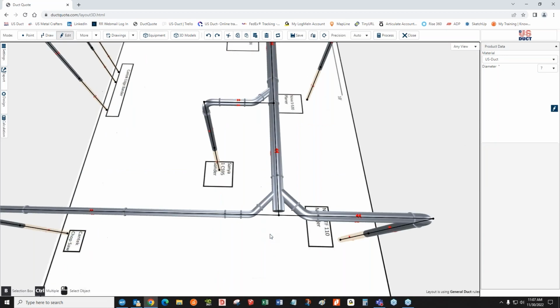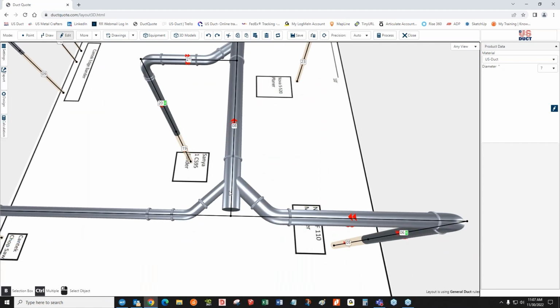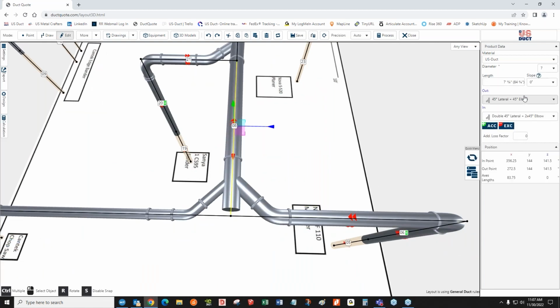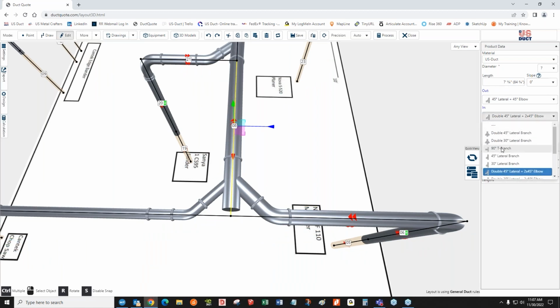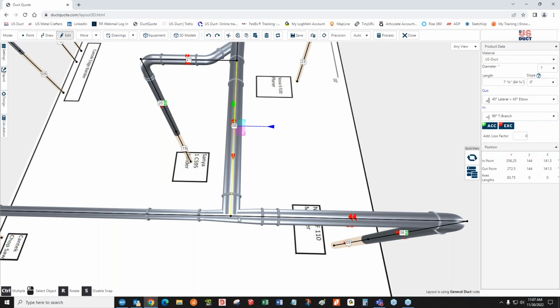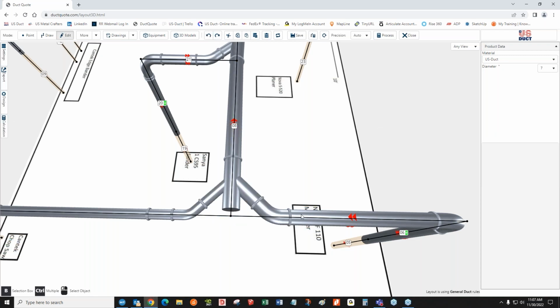We can also say that we're looking at this, and if I change what this is being told over here, where it is looking at a double branch, you can also see that this is obviously the center lines for a T branch, right? But what we know for a fact is those center lines don't define a Y branch. So most folks ask the question at this point, they understand the center lines aren't right. So how do I fix this?